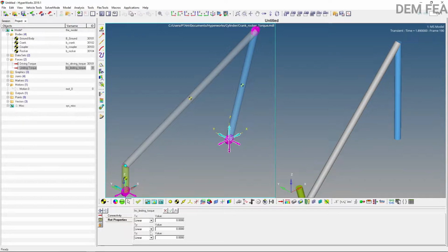Now for rotational properties, we are going to use Y. Why do we put in the Y, not in the Z? Because the rocker itself is rotating about the Y-axis, or the joints themselves are rotating along the Y-axis, and then the displacements and the velocities are along the Z-axis going up and down, not the X-axis. So we come to Ty and then we say expression like that.